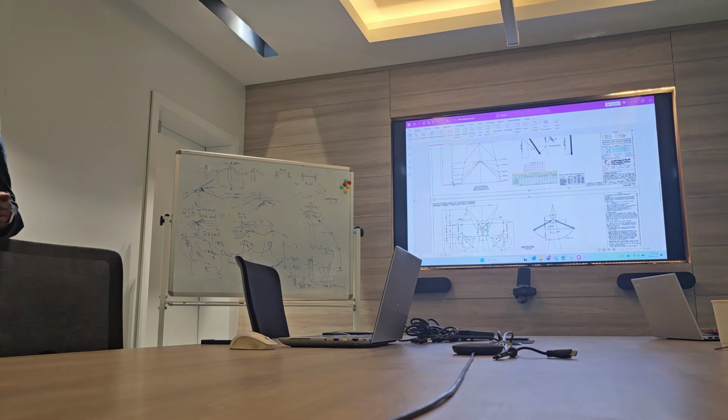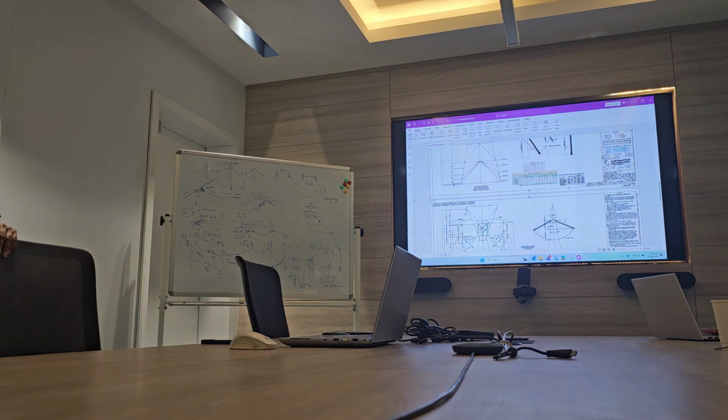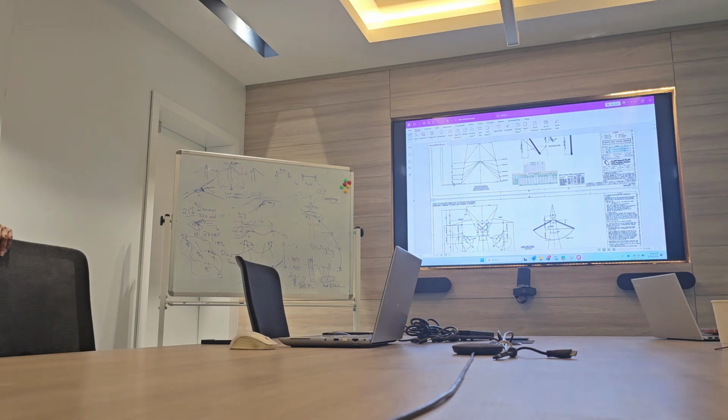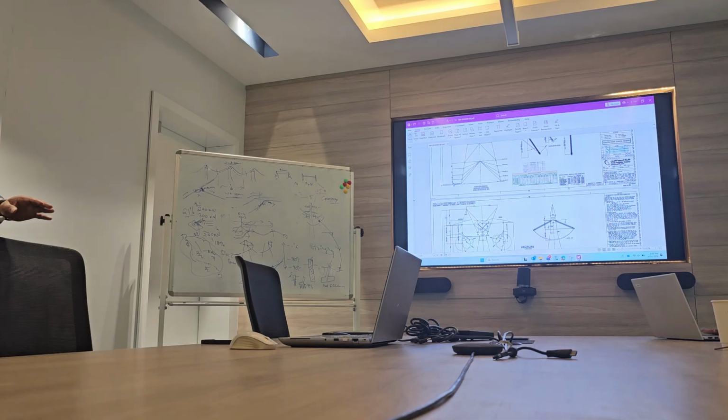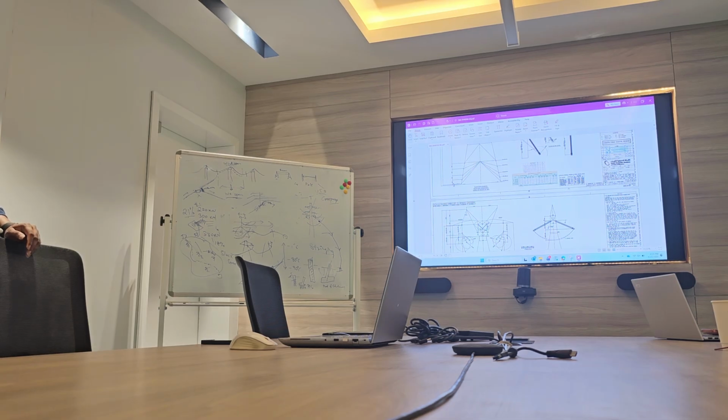I have a question. I know UGC, I worked with UGC. I know there are sections every 500 or 600 meters. Yes, in UGC there is a section every 500 meters because your drum length for the underground cable does not come more than 500 meters, for the joint purposes. For OHTL, 90 kilometers is considered as one section. No, not like this. Tower to tower.